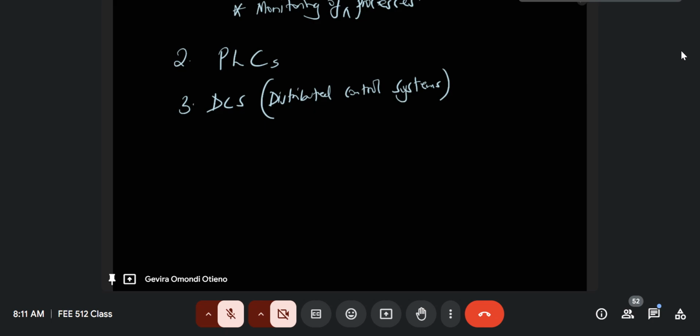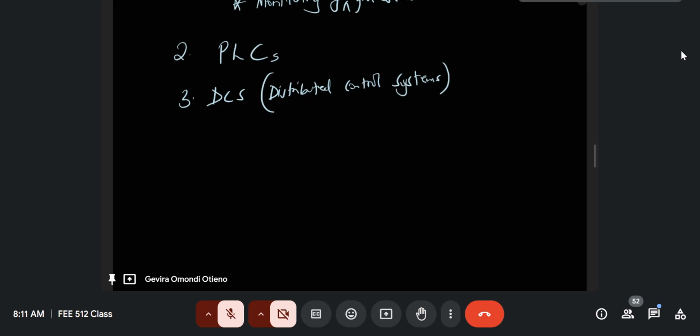So in order to control the flow or the system from Mombasa to Nairobi, they have connected PLCs and distributed them along stations all the way from Mombasa to Nairobi. Their PLC is not centralized, because they need to see which pipes are functioning, at what rate the liquid is flowing all the way, what stations they need to store it in tanks, what the levels of the oil in those tanks are, where they have leakages along the way, and so forth. So in order to effectively control and monitor the process of transporting oil from Mombasa to Nairobi, they need to have PLCs that are distributed.